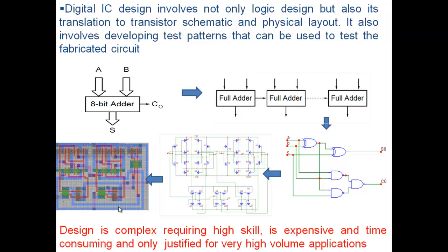IC design is not simple, it's complex. It requires high skill, is expensive, and is time consuming. And because of all these reasons, it's only justified if you have a very high volume of ICs, because the cost of developing an IC and the fabrication costs are justified only if the volumes are in millions. So if you are a designer making a stepper motor controller and you need a digital circuit, and your volumes are maybe 100 pieces or 1,000 pieces that you can sell, what do you do? Well,